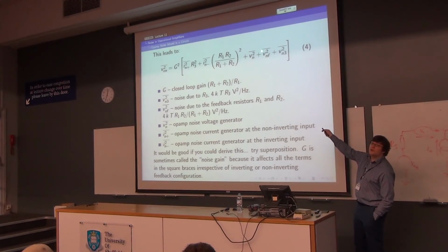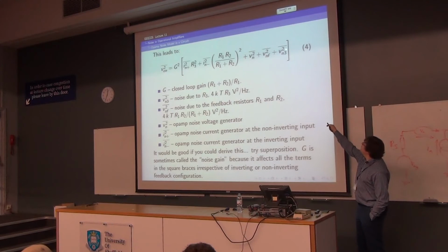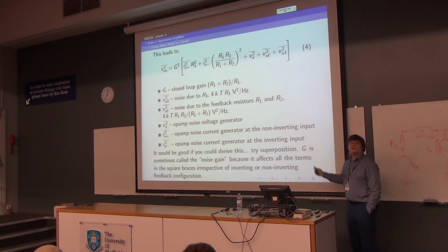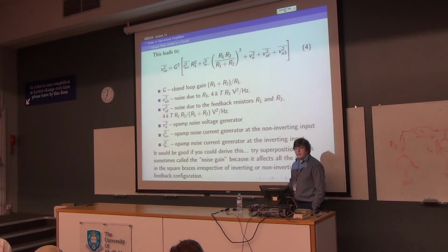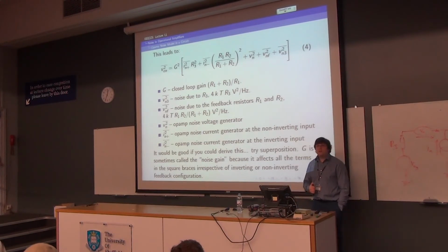So this is thermal noise of the feedback resistors, of which you are in direct control because you can choose their values. And then you've got a voltage noise of resistor number 3, which may be dealing with your offsets, or maybe 0. Happy with what all the terms mean? Yeah? Or no? Okay. So, non-inverting gain is also called noise gain.